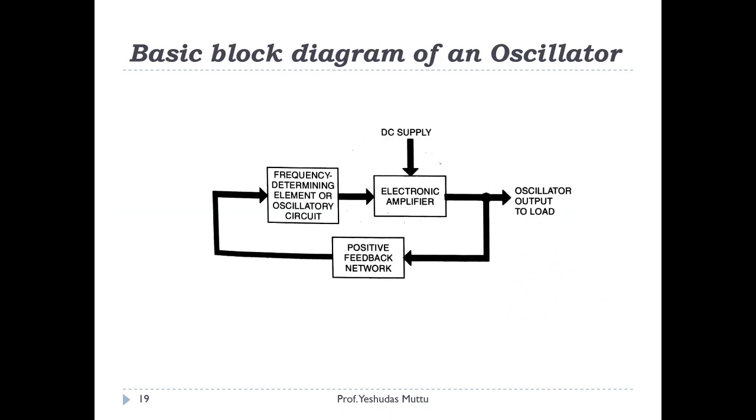To understand in more detail, let's have a look over here. This is the amplifier which I was talking about. There are some resistors inside, and resistors have free electrons inside. At room temperature they start moving, and that generates some voltage, named noise voltage, because of which I get some output over here. This output is fed back to the oscillatory circuit, and that is how things go on and on. I hope this concept is clear to you all, from where the oscillator gets the starting voltage.